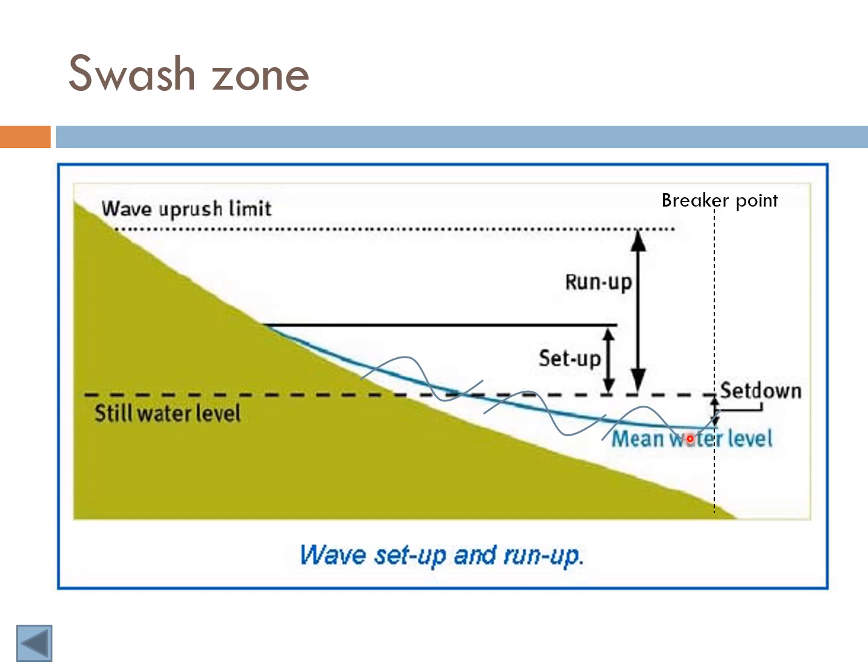So we will observe wave going up and down about this mean water level all the way to this point, which is the limit of the wave setup. Once the wave reaches this point, it will use its residual energy to wash up the coastline to this wave uprush limit. So this is the mechanics in the swash zone.